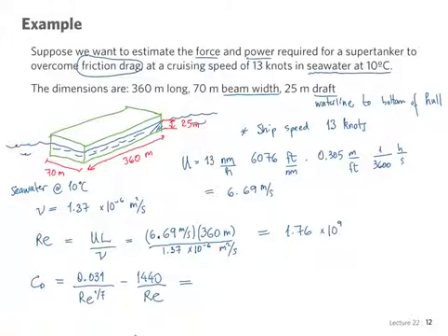Sorry? This is what we said just at the very end before the break, which was if you have a mixed boundary layer, you have to adjust for the fact that in the very front of the flat plate there will be a laminar region. And it's all empirical, so there's no analytical result here that we've used. It's been obtained from many experiments. Question?